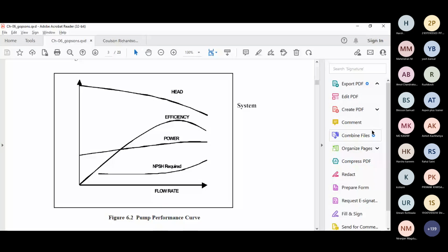और जो किसी ने बोला कि rho gh it's constant, but it will depend. Sometimes what we do, we give the head in terms of meter of that liquid. Meter of liquid column we say MLC. So if we are fixed कि हम वही particular fluid ही use करने वाले lifetime for that particular pump, then it is MLC. Otherwise we give meter of water column.